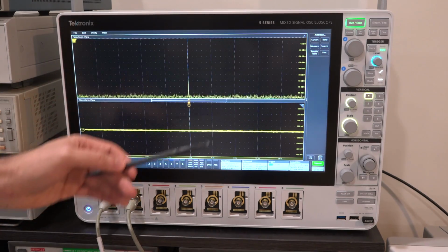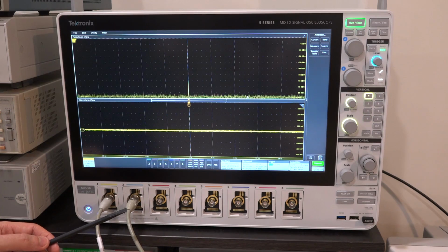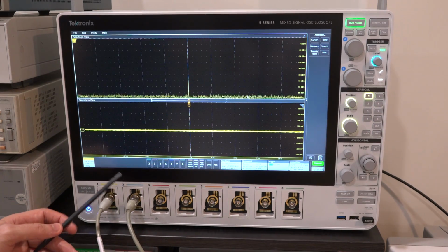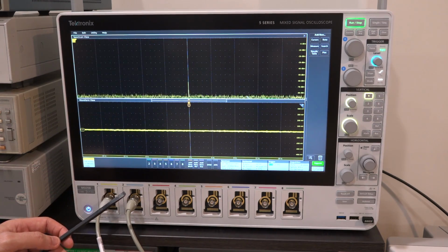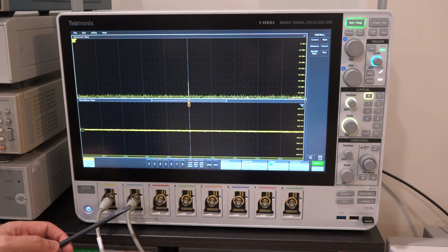Because the ADC has to run at a much higher sampling rate, its dynamic range, or its effective number of bits, is going to be quite a bit lower. Whereas you can easily use a 16-bit converter in a spectrum analyzer because you're looking at only the IF signal. Instead, you do down conversion with a sweep in order to be able to get the signal you're looking for.